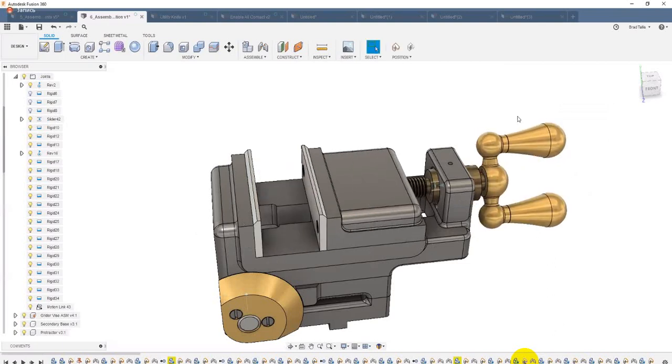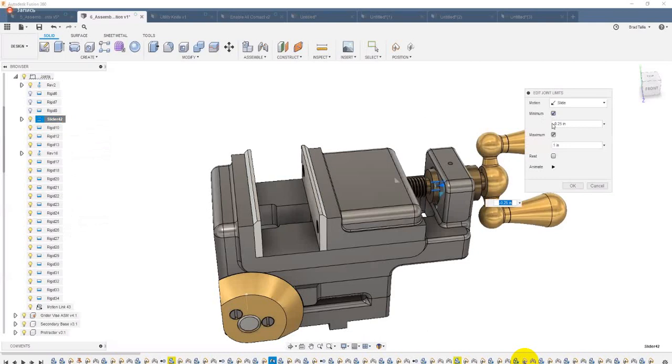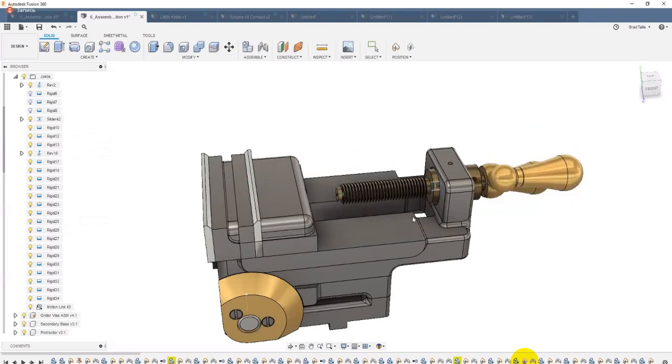And you can do this with rotational limits. Like I mentioned previously, let's say you designed a desktop robot. Maybe you only want to limit the base to rotate 180 degrees so it doesn't wind all the cables around itself, right? So you would set your rotational limit to 0 to 180. Okay. Now I mentioned there's a way cooler way. Check this out. I'm going to edit my joint limits and turn these off. So we're back to clashing in both directions.